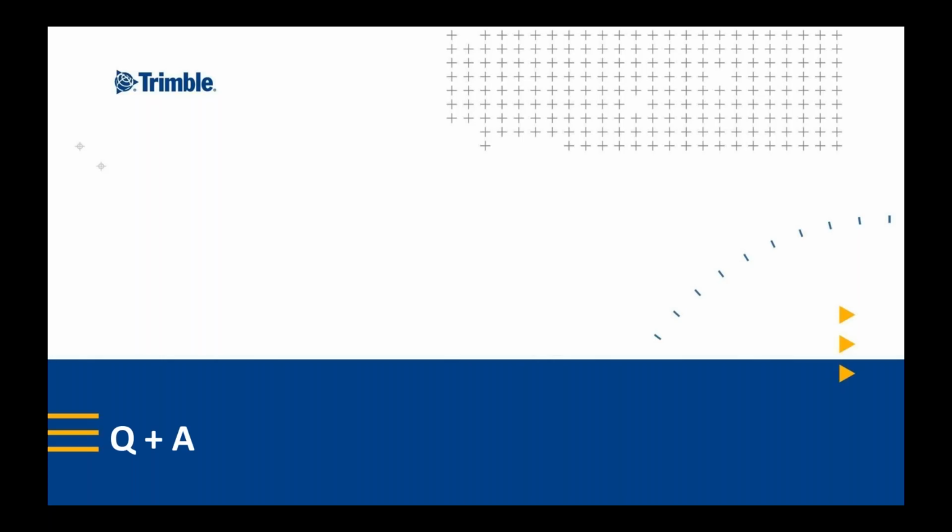Okay, so then do you then stake out those interpolated sections between the design stations, or is it primarily just along those stations that you've designed? We can definitely do either. Anywhere that those super elevation transitions occur, we would be staking those out in the field, and those would also be shown in our design as well. Anywhere that there's any of those kind of transitions, whether it's super elevations, widening transitions, section changes, any of that kind of stuff. And we can also stake as needed between any of those.